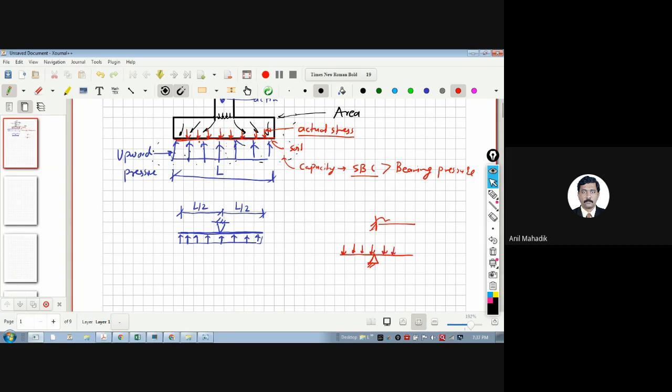Generally, we are used to seeing such kinds of pictures, with a downward force. As this is a balanced cantilever, it will offer a cantilever bending moment like this. In this case, it will be at the bottom. So 0 at the free end and then maximum here and again here. So this will be the M max, right?